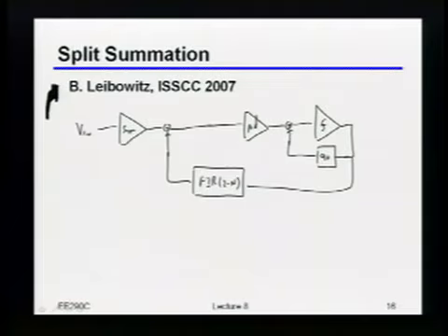So absolutely, it depends on how big the ISI is, but the only issue with doing something like this is that now, unfortunately, you're going to go through some nonlinearity getting from here to here, and you will still have that ISI left. Right? So if that nonlinearity is big enough, then that could indeed cause this to not actually work. In most link channels and most of the swings that I deal with, that's not too bad of a problem. But you're absolutely right.